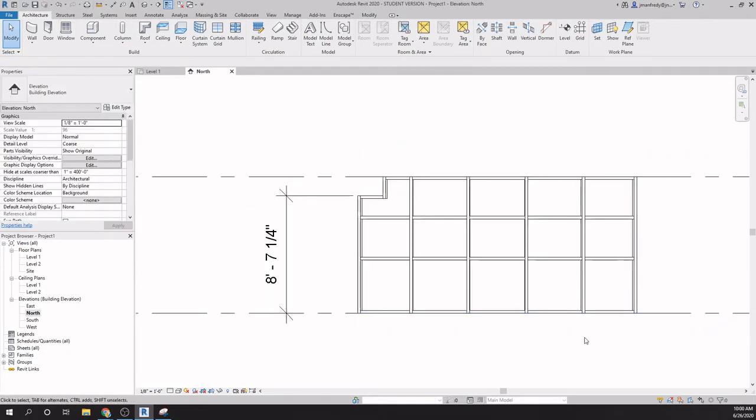So there's my notched curtain wall panel. There's the notch. I need to build a wall that's going to be placed right there. So let's try it using a wall on the second level that's been pulled down to absorb this gap, and then notch the wall and see if that procedure works as sort of an exercise. So let's go to the second level